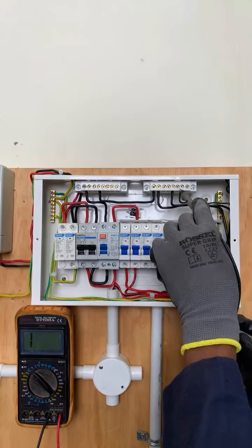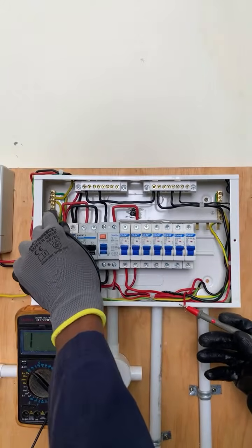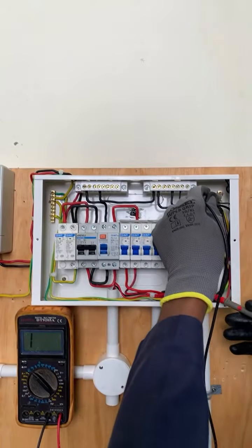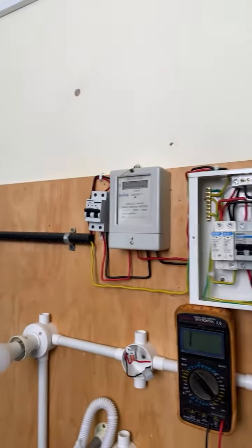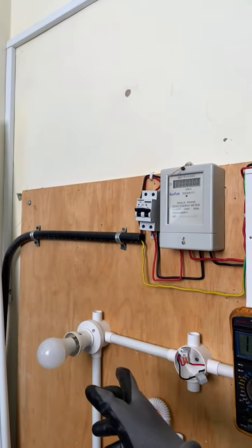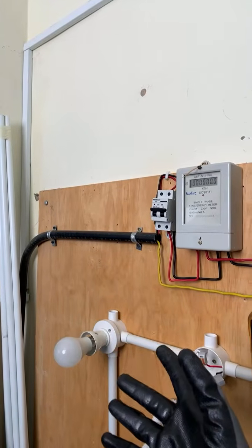Between the line and what? The earth connection. There is none. And you can start switching on every single light and testing. But again, instead of going through that tedious process, another thing that you can do is to simply remove the bulbs one by one. Assuming that you have the bulbs that are not lighting, remove the lights, the lighting fixtures, one by one.